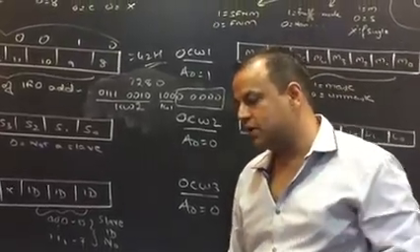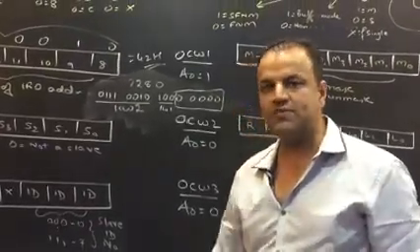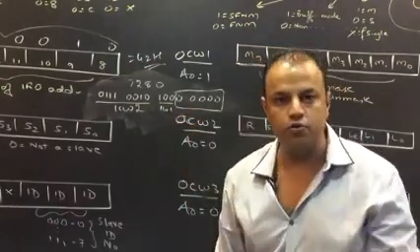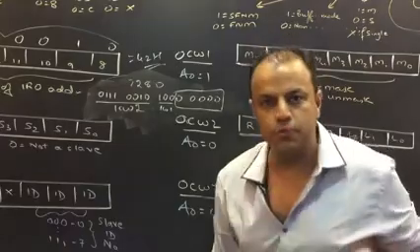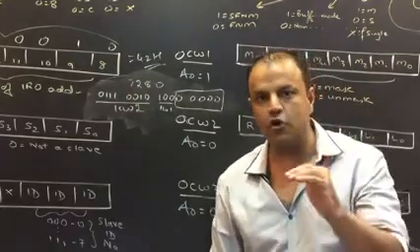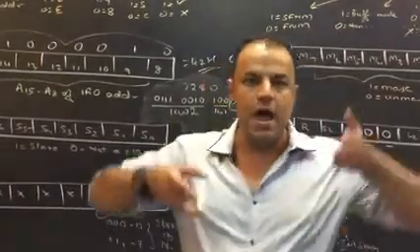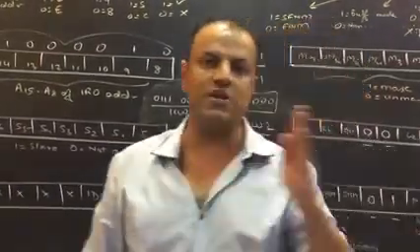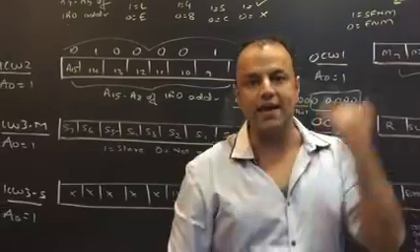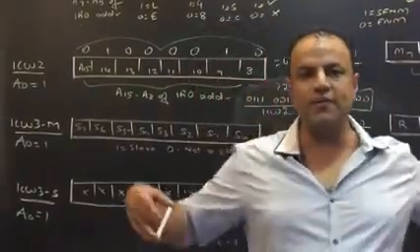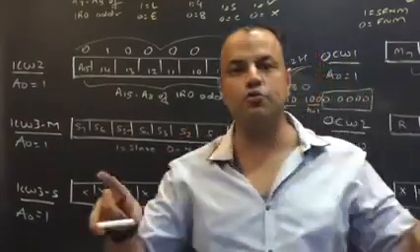Students say, sir, what if I store the ISR of IR0 at some address where this pattern is not 0? No, you cannot do that. When you're using 8259, these are the rules you're supposed to follow. You are writing the ISR of IR0. ISR is a program. Write it at a memory location whose last 5 bits are 0, because you don't give those bits to 8259. There is no provision to give those bits.